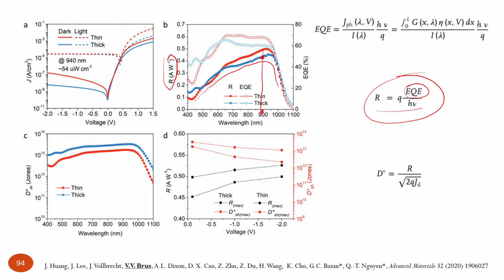Of course, if your signal is so fast that your diode cannot follow this signal, then it will not work in the same way with the same responsivity. But when you provide responsivity, in the data sheet for photodiodes you also provide the so-called 3 decibel cutoff frequency. That means up to which frequency this photodiode can be operated, and the manufacturer ensures you that this photodiode will possess this responsivity characteristic up to that frequency. If you go to higher frequency, then of course that's not what you should expect. So that is what we measure.